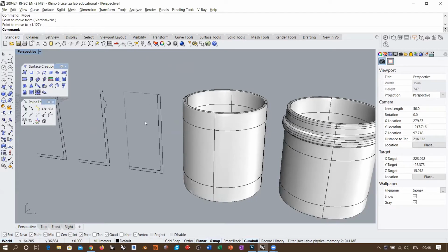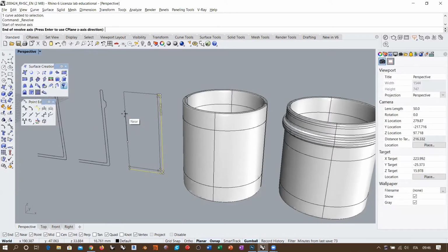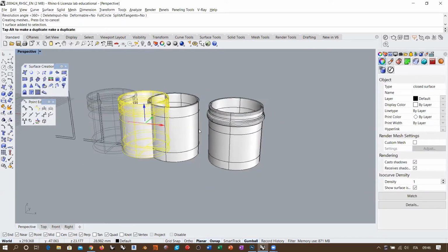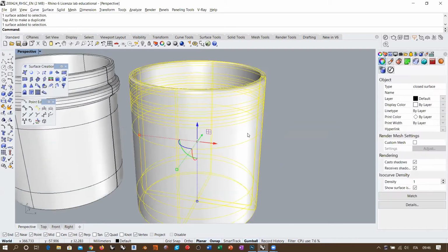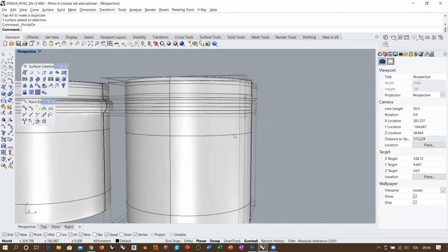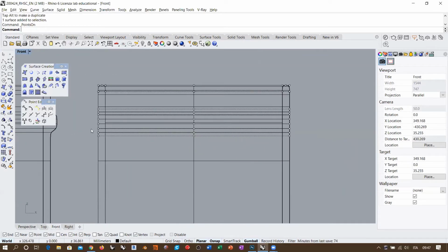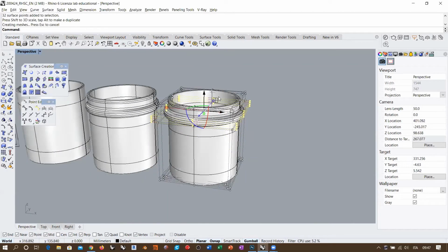Once I have the topological condition, we know that this will be taken into account during the revolve command, because we saw that the revolve maintains the topological complexity of the profile. So if I revolve this thing around this axis, even if it is not deformed, I already have the correct topological conditions for creating this kind of deformation. So I can do this once I have created the revolve. I can go into the front viewport, have access to this set of 1, 2, 3, 4 control points.